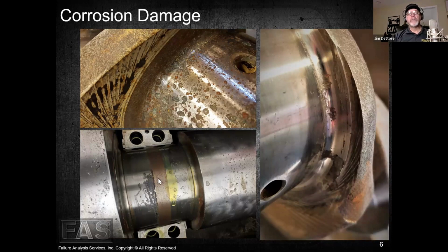One thing we need to keep in mind is that anytime we damage the surface, we're also generating secondary debris. That was the first podcast that we did on abrasive wear. So we need to ask ourselves, what type of damage could that secondary debris be doing elsewhere in the component?